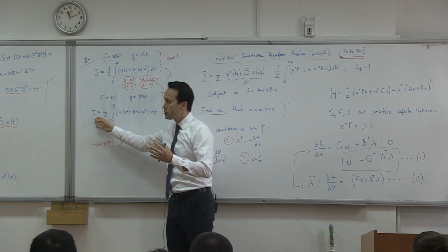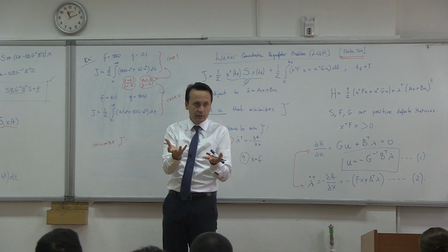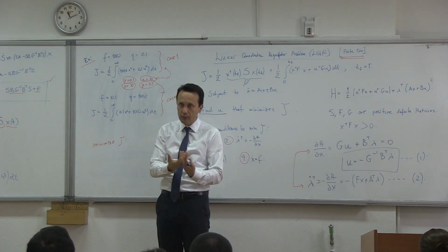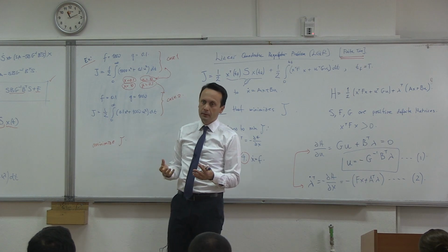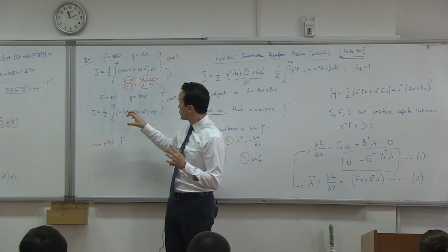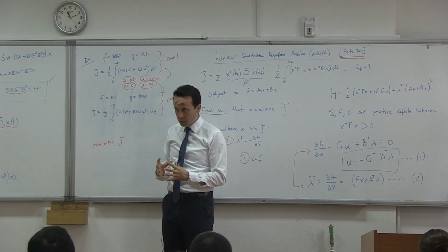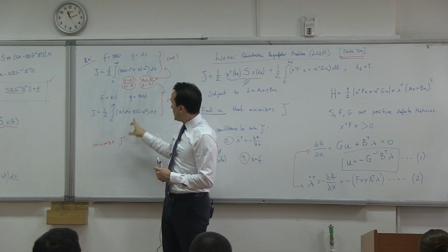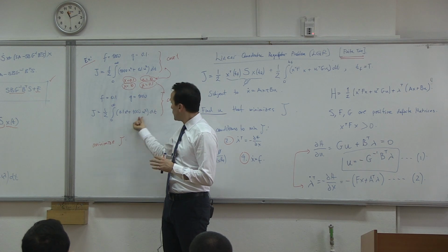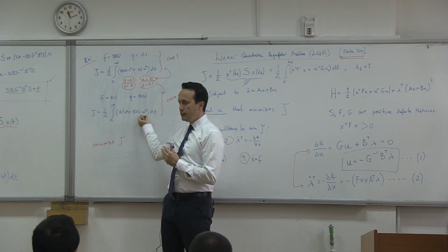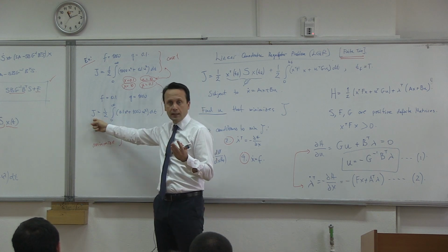So it will choose a solution because the minimization problem is choosing u's and x's. It chooses a combination of u's and x's to minimize j. That's the optimization problem. Right? The optimization problem will choose u's and x's to minimize j. That's what it's trying to do. So when I choose a large number over here, it will try to choose a combination of x's and u's where u's are small here and rather large x's over here so that you get this.